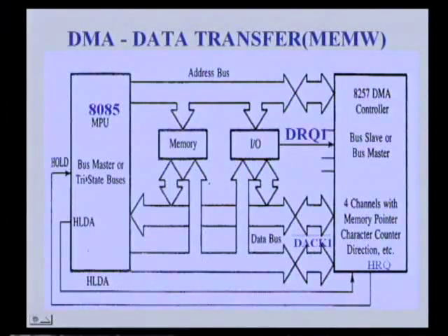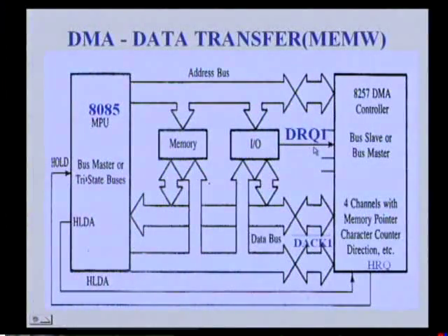And 4 I/O devices can request this DMA controller. Inside it there will be a priority resolver which determines which I/O device is to be served. After choosing that particular I/O device, this DMA controller will send an acknowledge signal to that particular I/O device, so that data transfer with that particular I/O device takes place. Let us see how data transfer occurs here.